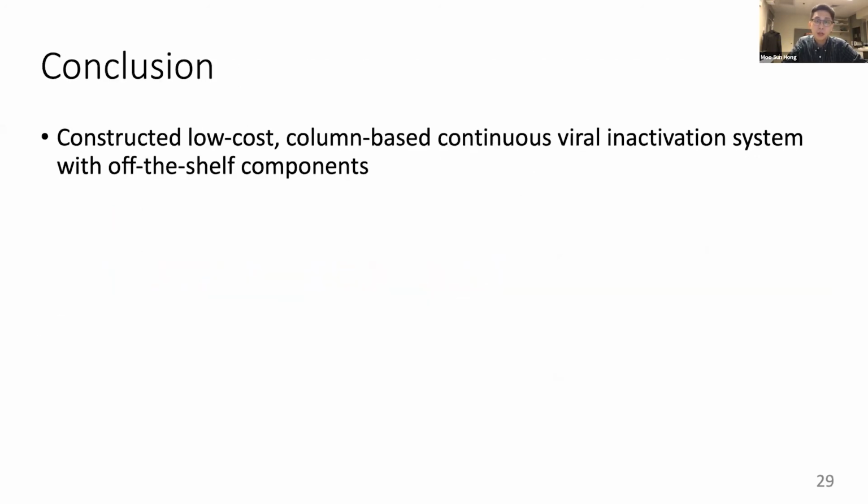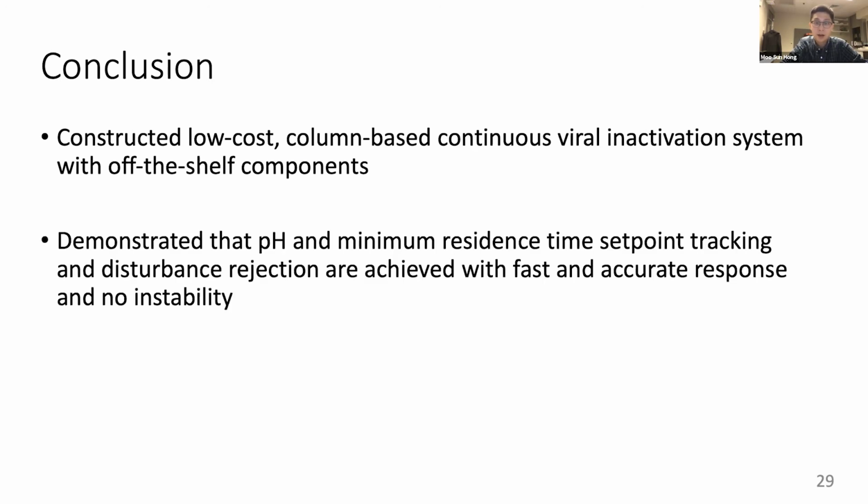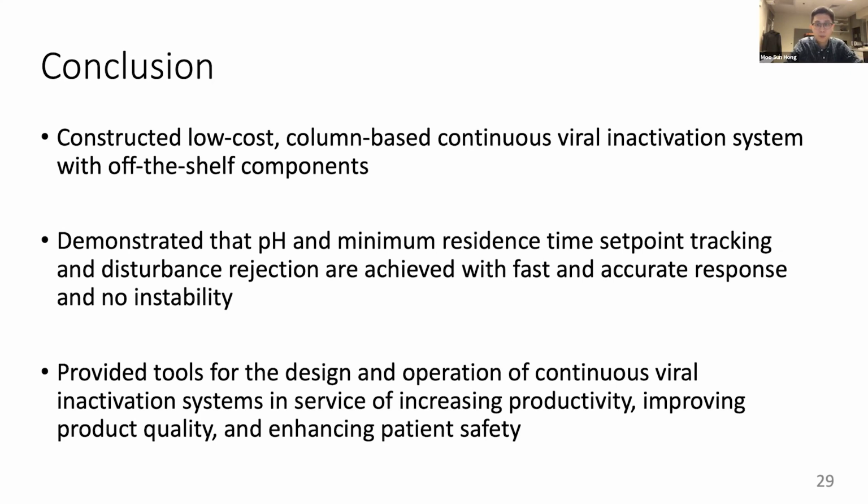So in conclusion, in this work, we have constructed a low-cost column-based continuous viral inactivation system with off-the-shelf components. And the controller validation experiments demonstrated that pH and minimum residence time set point tracking, and also disturbance rejection, are achieved with fast and accurate response and no instability. So overall, this work provided tools for the design and operation of continuous viral inactivation systems in service of increasing productivity, improving product quality, and enhancing patient safety.